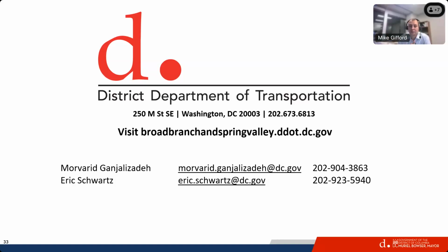So with the roof runoff, you're absolutely right, that would be a great thing to be done. Where this project and that diverge is, we design our facilities to accommodate the roof runoff where it occurs on these streets. DDOT's mandate really is to treat the water that is in the right of way, which largely is the roadways. The items that are coming more from the private property tend to be more of a DOE situation, just because it's a little outside of DDOT's purview. But yes, if there are opportunities to decrease the runoff into the roadway, to do rain barrels, to do dry wells, that is always helpful in general for assisting with treatment of water in the separated sewer system.